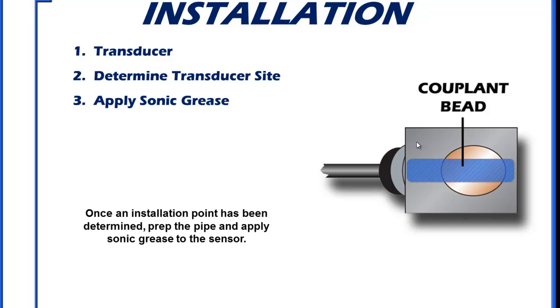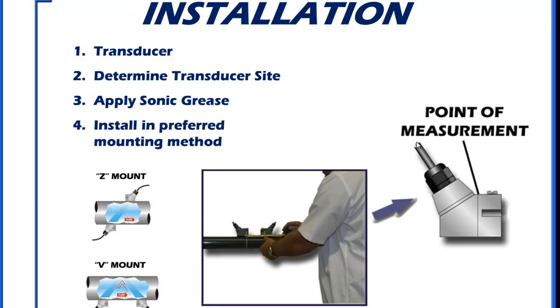Depending upon your application, you have different greases there. So the standard silicone grease covers you under most temperature conditions. If you had a high temperature application, we have some different greases there that can keep their consistency at a higher temperature. Water-soluble greases are an option. We have them. We don't normally use them for dedicated installations, but if you need them, they're available. But they do tend to wash out. Remember, they're water-soluble, so if you get moisture, they'll drip out. So they're not designed for long-term installations.